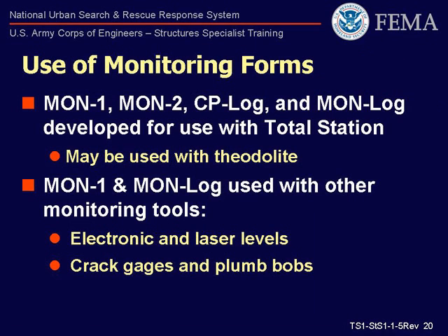While these forms have been developed for use with a total station, they can easily be used to log recorded interval data for other monitoring devices as well. What is important here is to accurately document movement in the hazard and communicate that movement clearly.